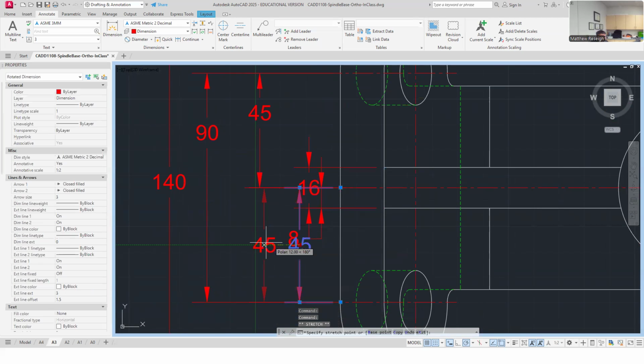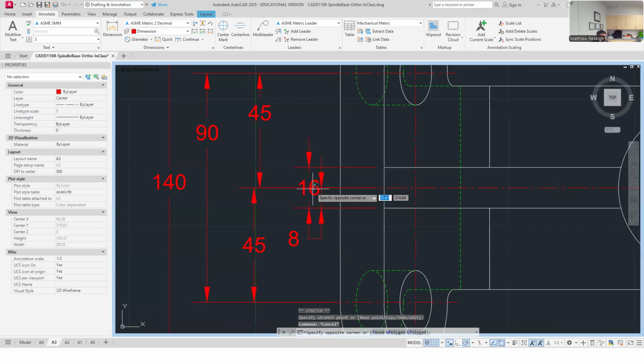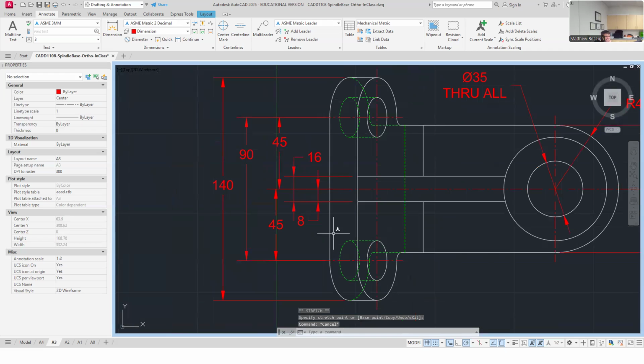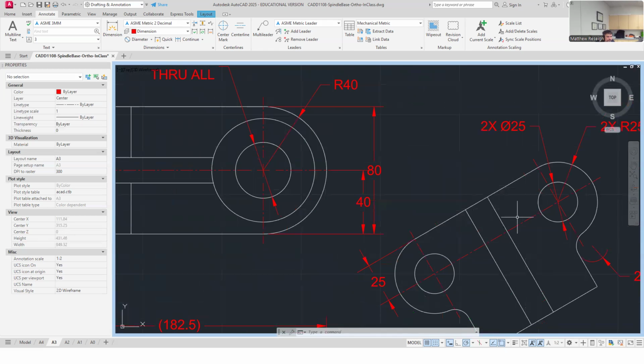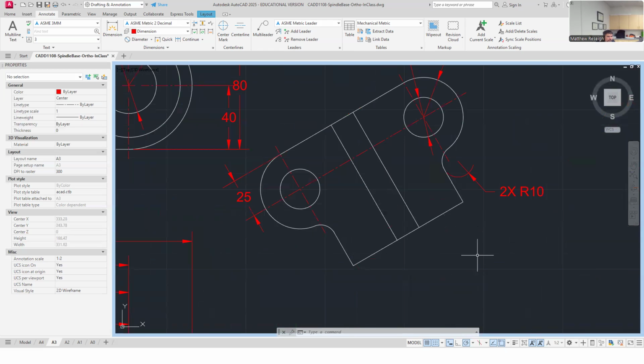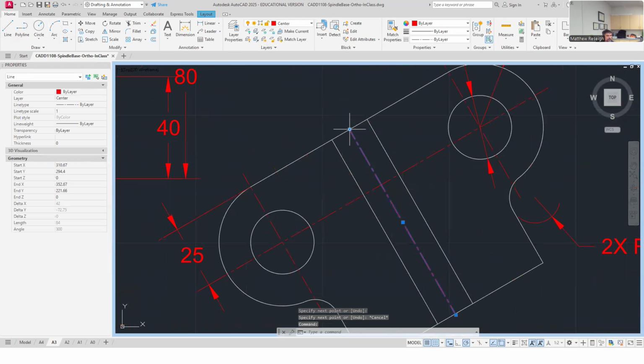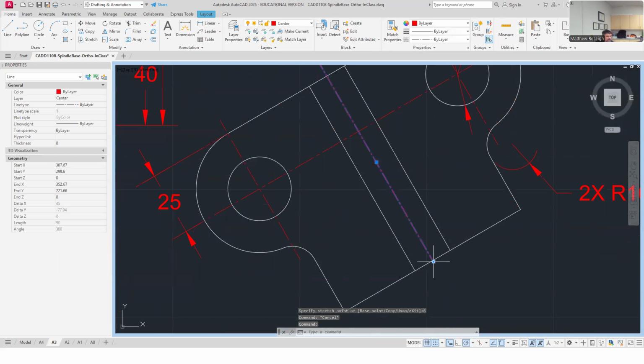And I'm going to pull this one out in a way because I'm definitely getting busy here. And then I'll clean this up a little bit more. I'm just cleaning up a little bit now. Might it not be a little bit better for clarity's sake to have the gusset dimensions put on the auxiliary view? You could. They could go here, right? And I would do the same thing where I'd apply, I'm on the center line layer right now. So if you did that, you would just want to add a center line to your part here. And that's not a bad idea anyway. If you're going to dimension to it though, base it off the center line here for sure. And so I'd have to add this, and you could do that.